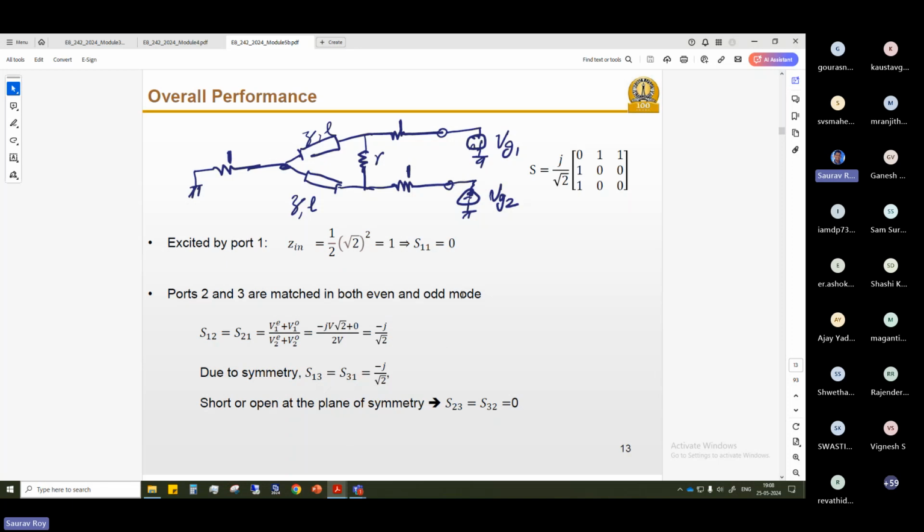So yeah, this is the analysis of the Wilkinson power divider. It might be as old as 50 or 60 years, but it's still very much useful. You can build on it and make much more complex networks. But in this very plain form, just adding a normal impedance and quarter wave line, you can make very simple and useful circuits. You can make a power divider into half power, half power.